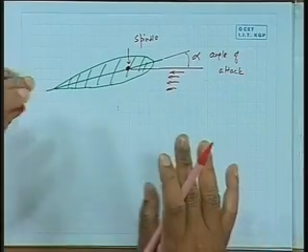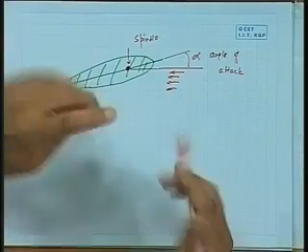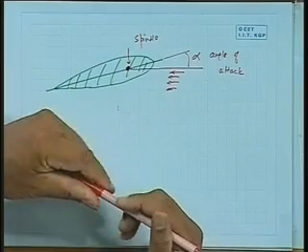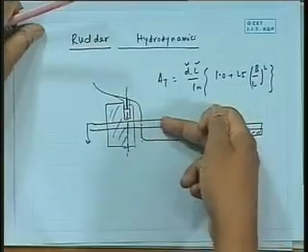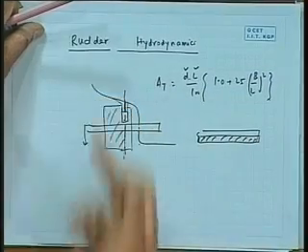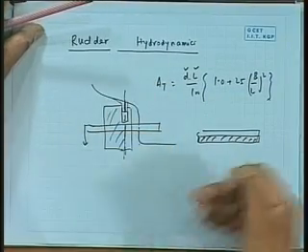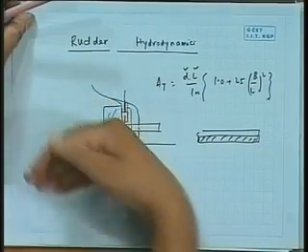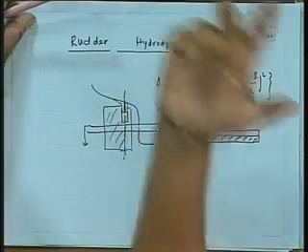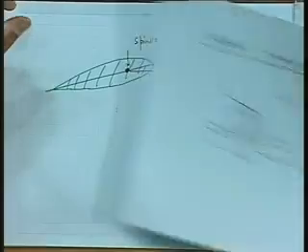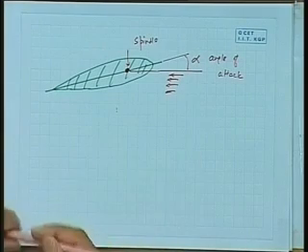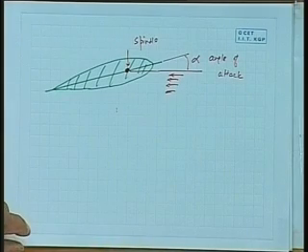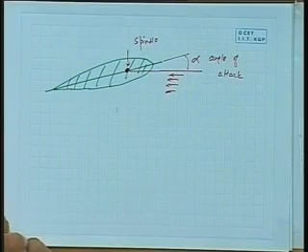Let me again say, if you take a cross section of the rudder, see, first of all, why cross section for hydrodynamics? It is only obvious because you would expect the flow along the rudder to be along this line, not having a vertical motion much. So any cross section you take, you can find out, and you can take each cross section, add them up, you will get the total force more or less. So therefore cross section is a very logical approximation, and I will just want to show or tell you what kind of forces will be acting on that.